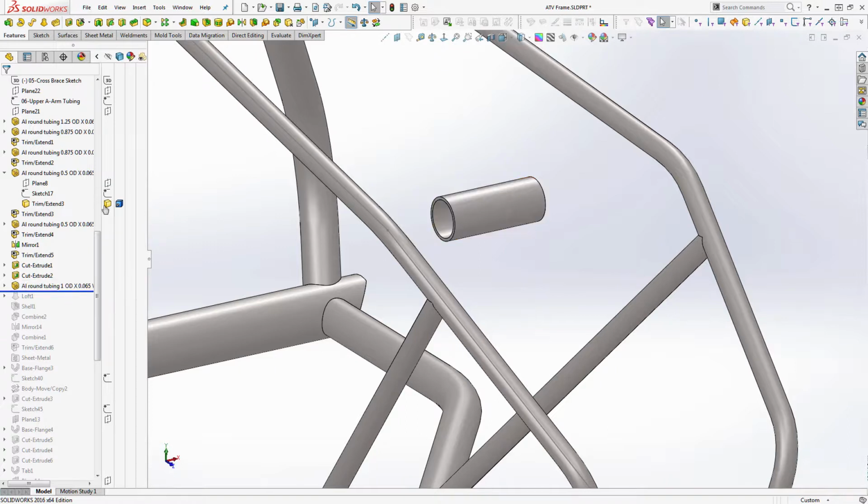What I did is I have that original sketch there that was this cross tube. The original cross tube was smaller. This tube's 1 inch, this tube's half. That's roughly double the size. It's kind of a poor example. It can be done, but even the way you would crush the tube, most people aren't going to use a form. They're just going to put it in some sort of vise mechanism. So the way it's being drawn here is not exactly right.